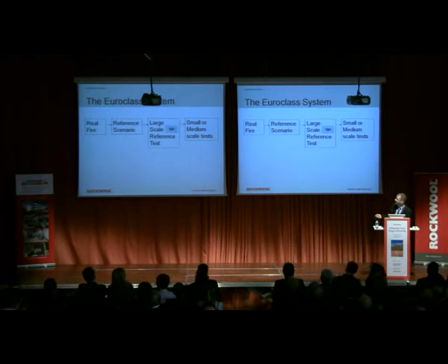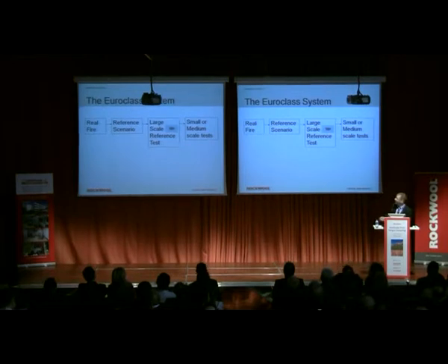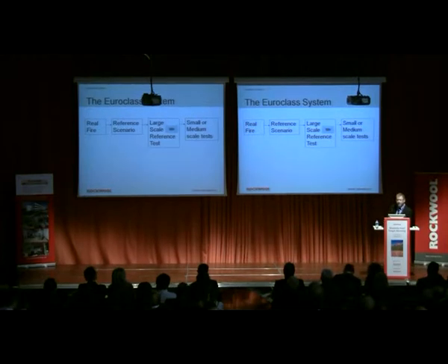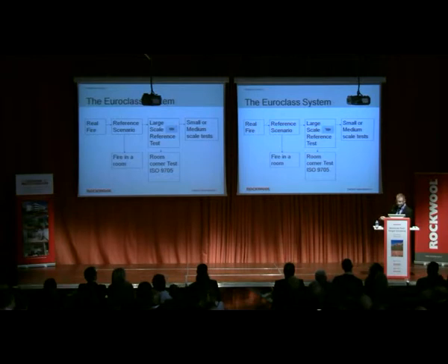We create a reference scenario and a large-scale reference test, and then we have these small or medium-scale tests to simulate what will happen in a large-scale fire. So, for reference scenario in Europe, we have a fire in a room, and large-scale reference test is room corner test, ISO 9705. But what we commercially measure is SBI.